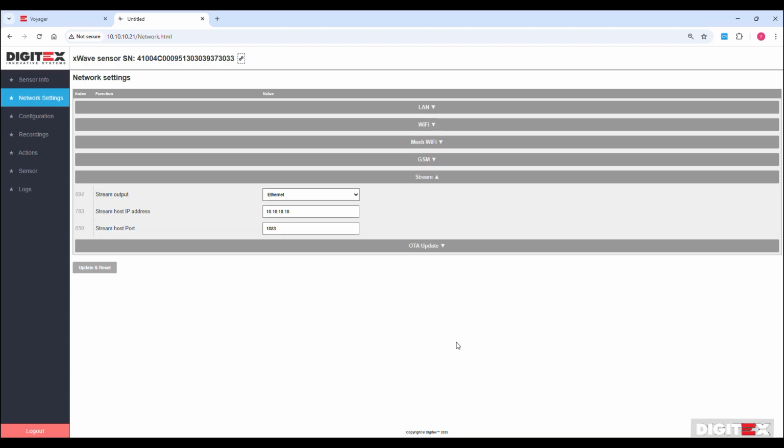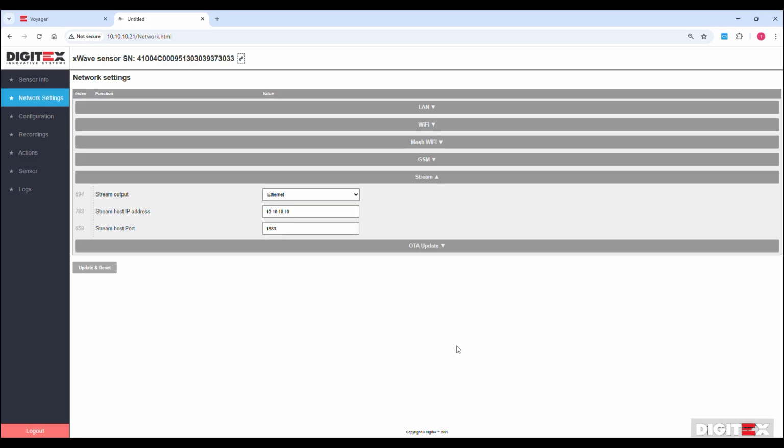The next option is to configure the streaming functionalities of the device, meaning how we would like our data to be streamed to the centralized unit called Explorer Premium. We have several options here, meaning that we can stream the data via Ethernet, via wireless, via mobile network, via mesh, or auto configuration. Auto configuration is a specific option which is used for portable equipment, meaning that when doing ambient vibration measurement, actually field tests, we often need to switch between wireless and wired communication. So the auto option is basically developed for this purpose,